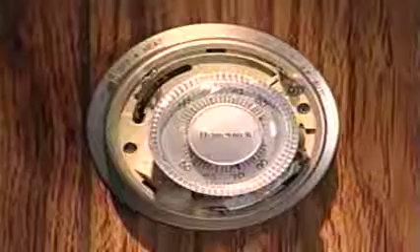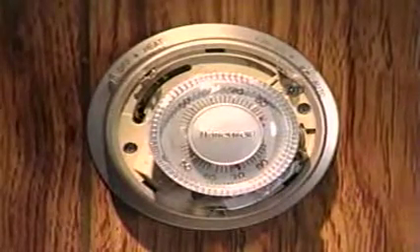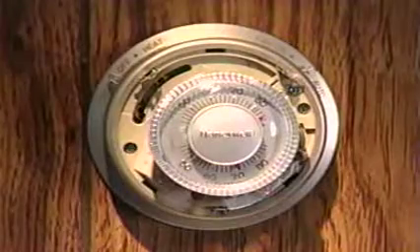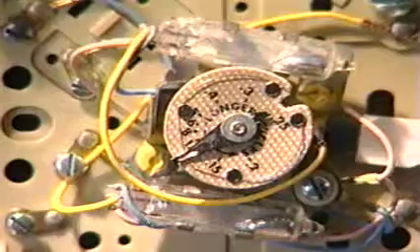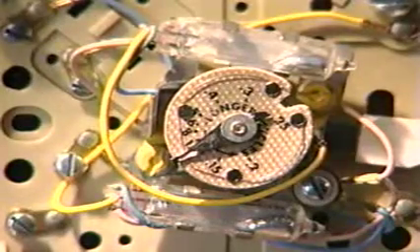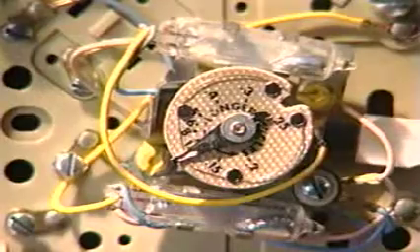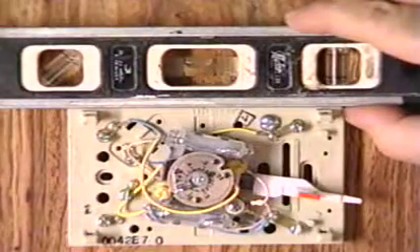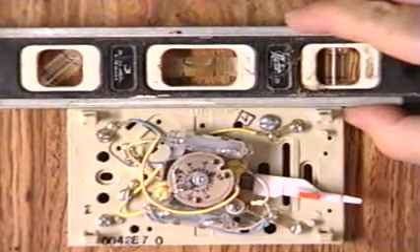When checking a thermostat, it's important to remember that the thermostat is a set of switches that controls the operation of the other system components. Each manufacturer uses a different labeling legend, so be sure to have the service booklet available. Many thermostats operate with mercury-filled bulbs that are connected to bimetal strips. These thermostats must be mounted perfectly level to ensure proper operation of the system.